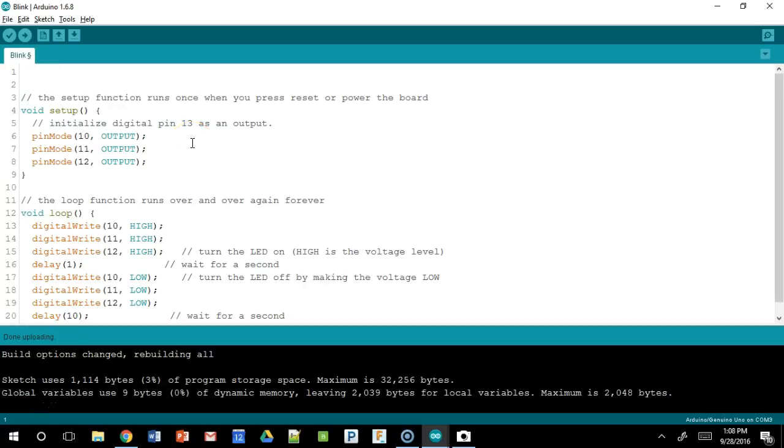In C-based languages, like what Arduino uses, we are going to write the pound sign and then define, hashtag, if you must, define, and then we are going to type in a name of something, and I'm going to say red pin with an underscore. We don't use spaces when we're creating variables like this, so an underscore would be a way of essentially creating a space. And I like to use all caps when I'm doing any kind of constant. This is what we're doing, where it's called defining a constant.